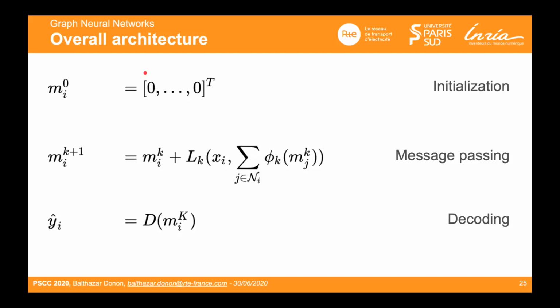Maybe I may complement this, because my question is that, let's say the AC power flow may have multiple solutions, right? Mm-hmm. And so even if you formulate it as you have formulated it, you can have several solutions. So how do you make sure that you are converging to the regular solution, which is usually obtained when we use a flat start in the AC power flow?